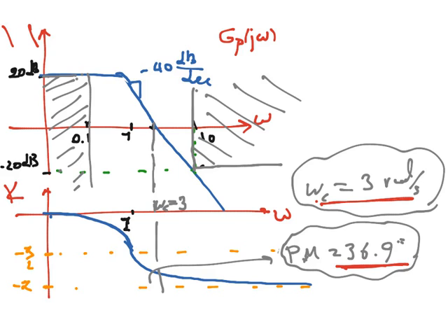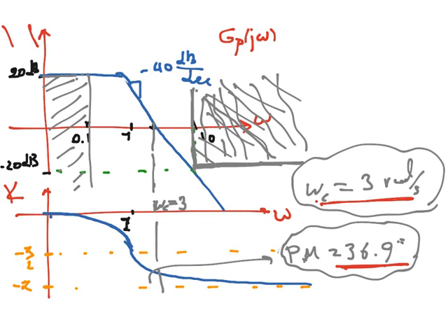And we also can determine the dangerous areas for the attenuation of the noise and for attenuation of the disturbance. So this is the area in which our amplitude Bode plot shouldn't enter, otherwise the noise will not be attenuated by the given factor. And here is the area for the attenuation or rejection of the disturbance.